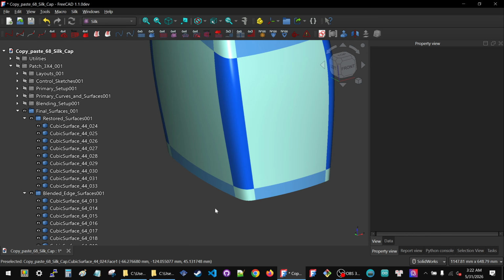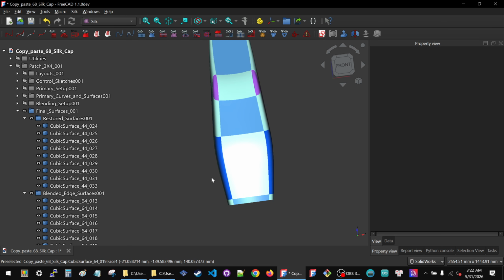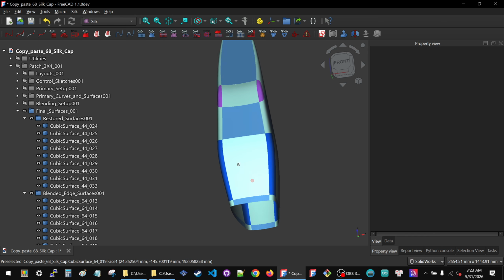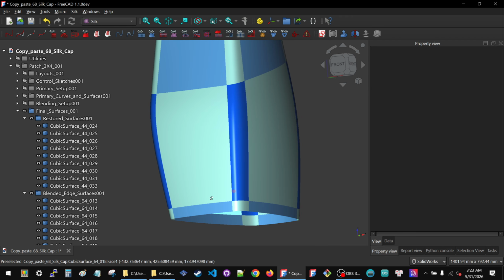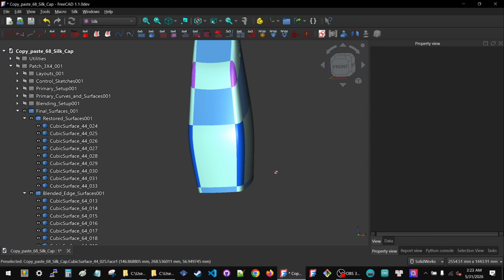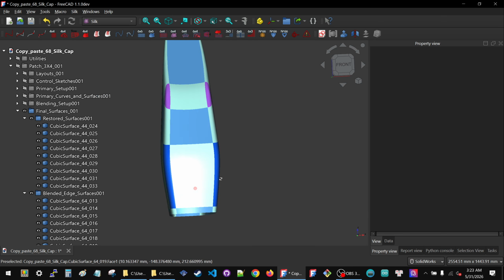Someone in the comments for the video when I made the flat cap using the part workbench said that filling surface is parametric. So if you use that tool, it could close the bottom parametrically. So you're welcome to try that. What I found is that object often breaks. I use it, but only at the last minute because it often breaks. And since it's harder to use than the shape builder, I need to do more testing before I recommend using it all the time. But you can go ahead and do that. All right. Personally, I don't care right now. I want to go back to pure silk, so to speak.